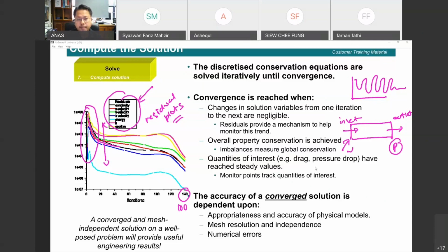So to do that, the job of the simulation is to find the velocity at the outlet, because we did not specify that. In order to find that, it needs to make some educated guesses. For example, let's say the final value at one point is 2 meters per second, just for example.